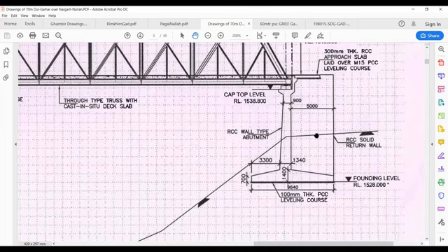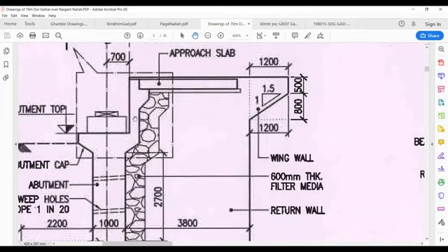और उस soil को वहाँ पे basically to ensure that it is retained in that area, कि slab नीचे ना बैठ जाए, उसके लिए you put walls here कि soil अंदर ही रुका रहे. This thing it is also there कि because we don't want soil to fall over here or bearing के साथ interfere करे. So this wall here, it actually encapsulates the soil. This wall and dirt return wall, they both together encapsulate the soil behind abutment, so that it does not flow away or does not get washed away.